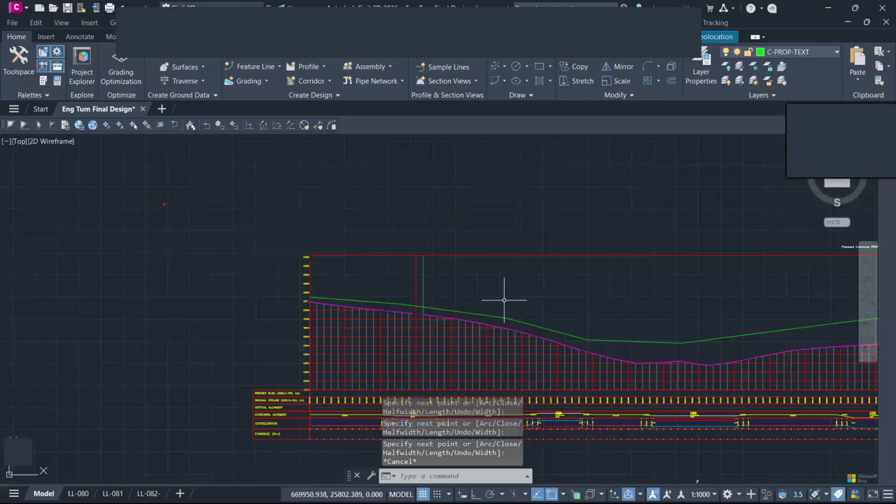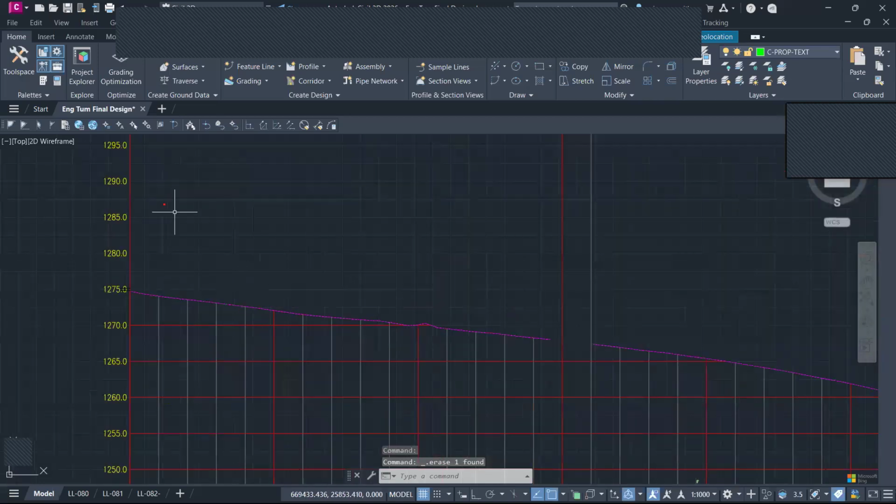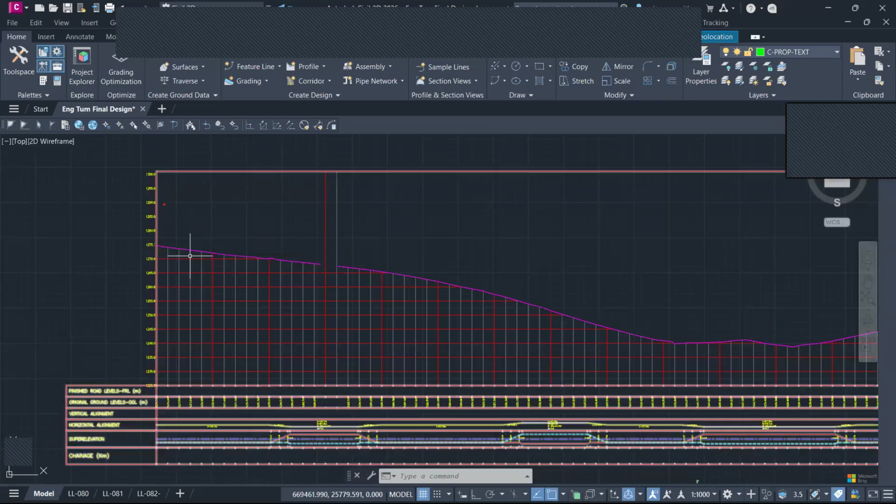No, your starting point is the existing ground. So first, make sure that you flush your design level with the existing ground. And then, with the considerations that we'll be looking at, drainage, safety, stopping sight distances, you keep adjusting. And then after that, you can incorporate the various fill layers that we have in the section.